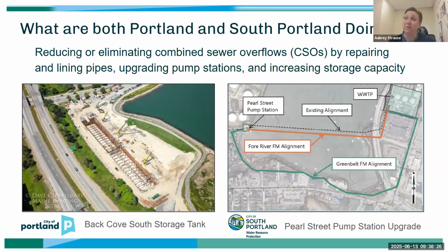Talk about expensive. The picture on the bottom left is something that you've probably seen, even if you didn't know what you were looking at. This is along 295 in Portland, along Baxter Boulevard, and it's one of the combined sewage storage tanks that the city of Portland has had to put in. The others were under Baxter Boulevard. What these incredibly huge tanks do is, during a storm event, combined sewer systems flow into them. They're huge underground tanks. So those tanks fill up during that storm event.